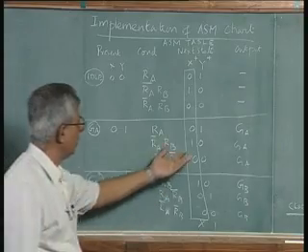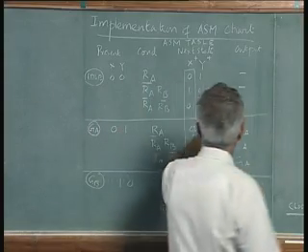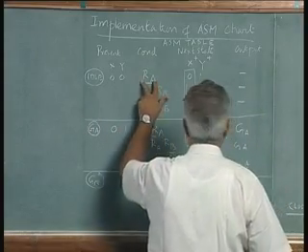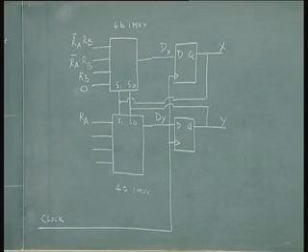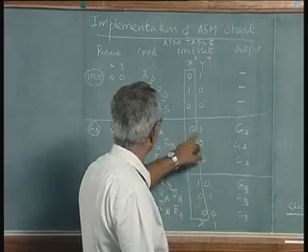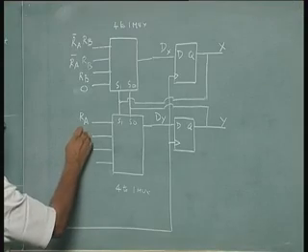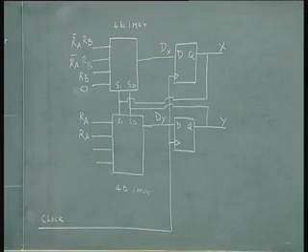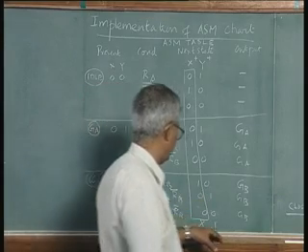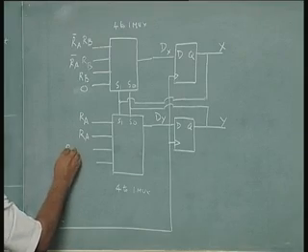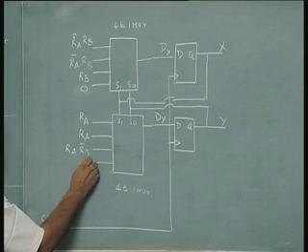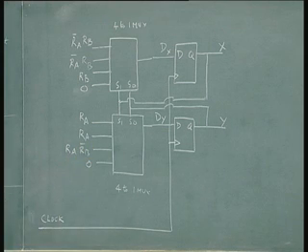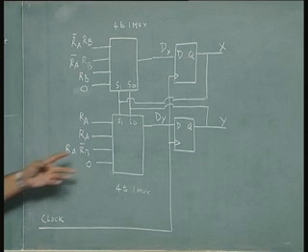Similarly, I can quickly do this for the second flip flop. For Y, condition RA leads to the next state being 1 for flip flop Y. Here again RA leads to the next state being 1, the design is so simple as you see. Here RA RB bar leads to the next state being 1, and this again I will put 0, so that any false inputs end up in the 0 0 state.